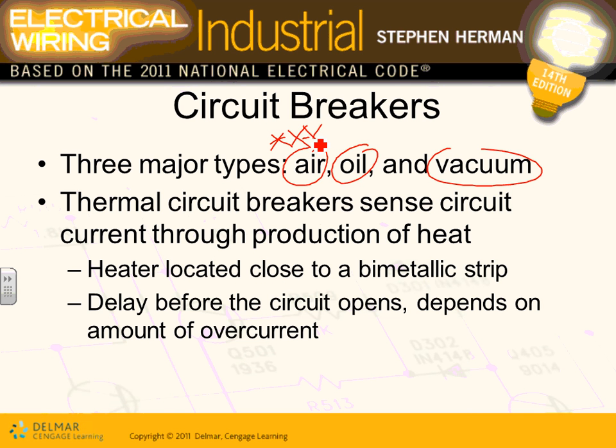What is a vacuum circuit breaker? They have a little tube with contacts inside it, and they remove the air from it, so it's a vacuum now. So when you open these contacts, you don't get that much arc.